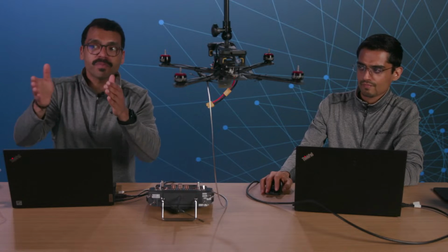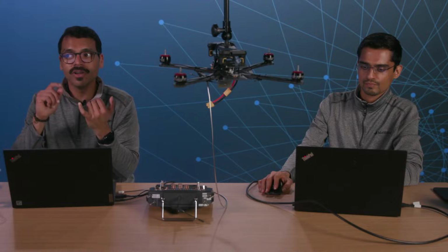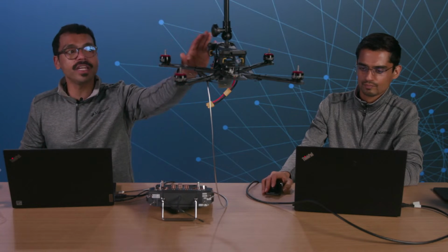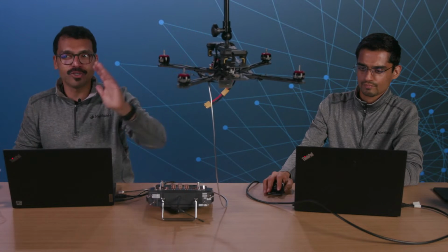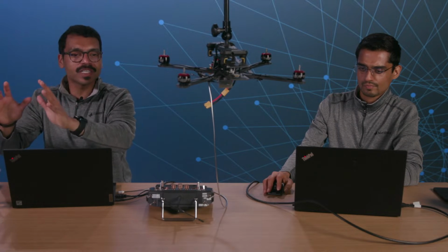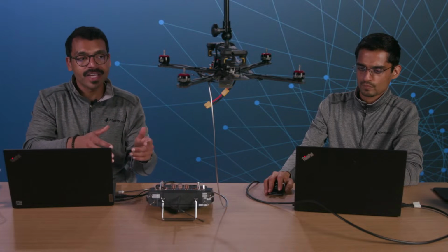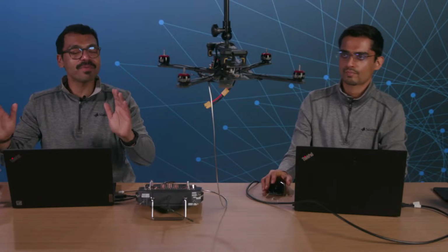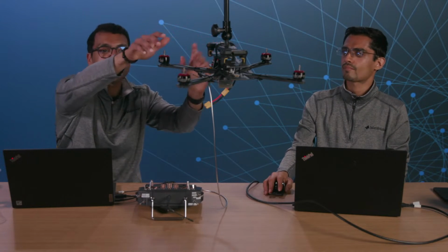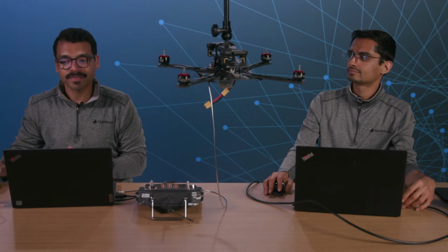So first make sure you do it with the Simulink Data Inspector, so you know: is your attitude controller giving the right data based on the current yaw? I'm still reading from these sensors. I'm still sending data to the same motors, but I'm just making sure that everything works before I go and plug in my battery. And then I can plug in my battery and do the same test with my actual flight controller. And then once I'm happy with that, I can take it off this rig, I can put the propellers on, and I can go test it in actual flight.